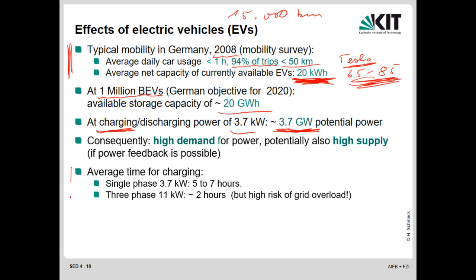Now, the interesting point is the average time for charging. How long do they need to be recharged? If the battery is completely empty, 20 kilowatt hours would need, with single-phase simple charging, 5 to 7 hours. If you allow a little bit more, with 3-phase charging, you have something like 11 kilowatt, which would mean around 2 hours. If you would agree to have just 80% state of charge, it would go even faster.